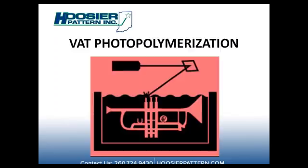The first is going to be vat photopolymerization. It is an additive process where a vat of liquid photopolymer resin is cured through a selective exposure to light via a laser or a projector, which initiates a photopolymerization and converts the exposed area to a solid. This process is also called by other names that are trademarked by the machine manufacturers. Most of them we've heard of.